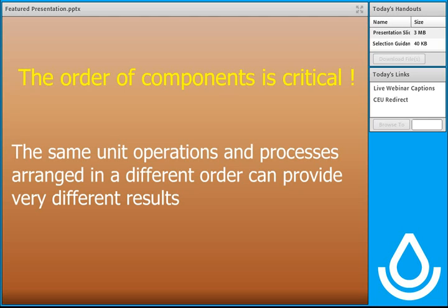Understanding the operational order of the system components is also very critical. See, the same components can be arranged in a different order, and yet they may have a completely different output in terms of the nutrient fate and also the form. Now, for example, some anaerobic digesters require very low solid contents, such as an induced blanket reactor. And in this case, solid separation likely will occur before the manure enters the digester. Whereas in other situations, like with a plug flow or a complete mix system, solid separation is likely to occur after digestion. So the order of the unit process is extremely important and can impact the results. So we need to make sure when we're diagramming, we diagram in the correct order.